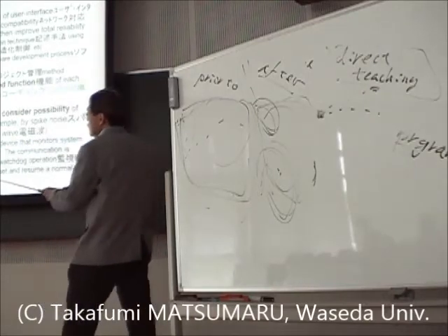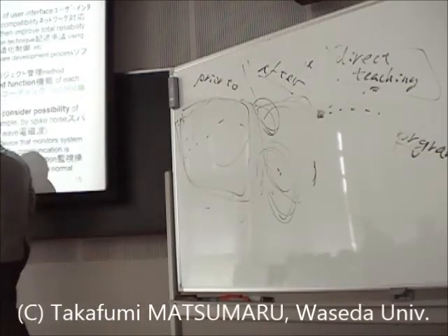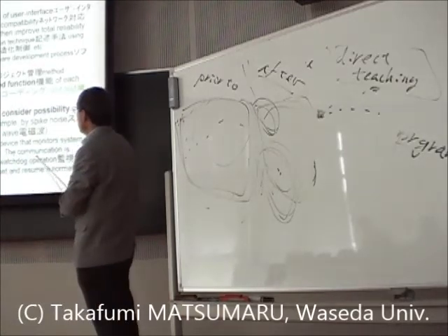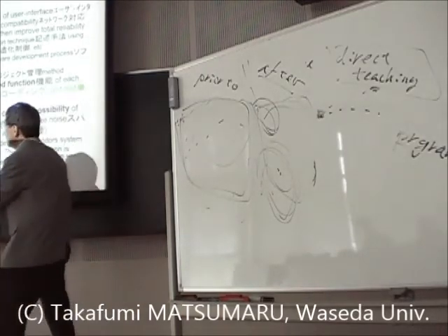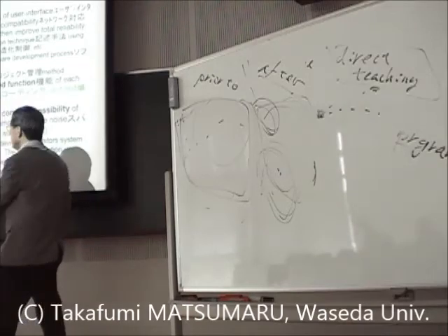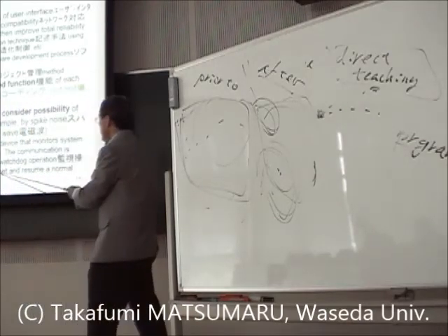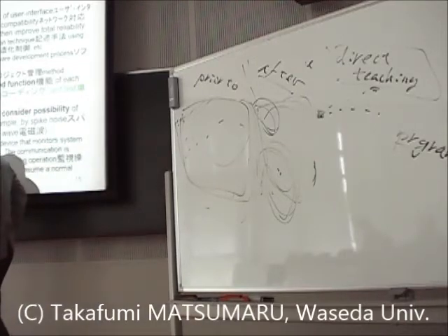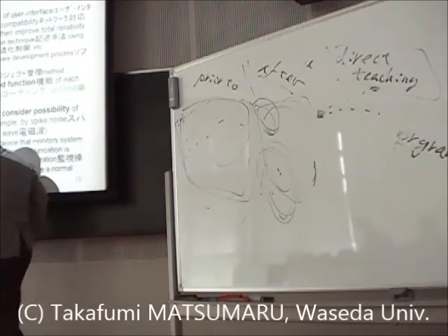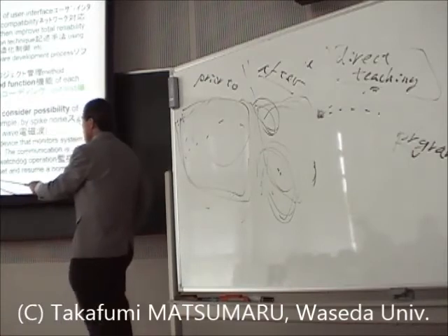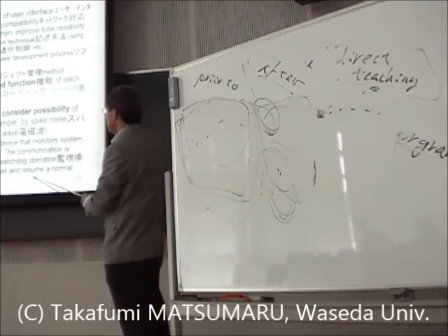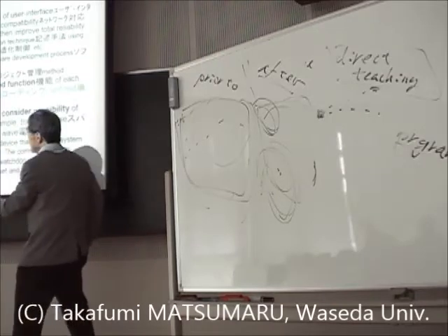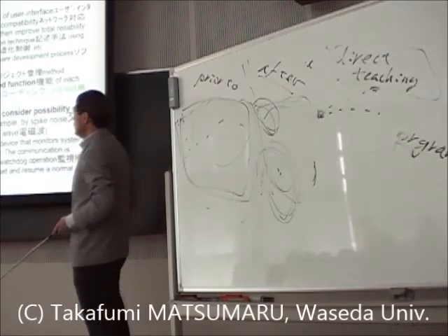that monitors the system health and functionality by communicating with the system software. The communication is through a dedicated device driver or device timer. In regular watchdog operation, if the service pulse writing is not executed, the system will be reset and resume a normal condition, supervising software operation using a hardware method.